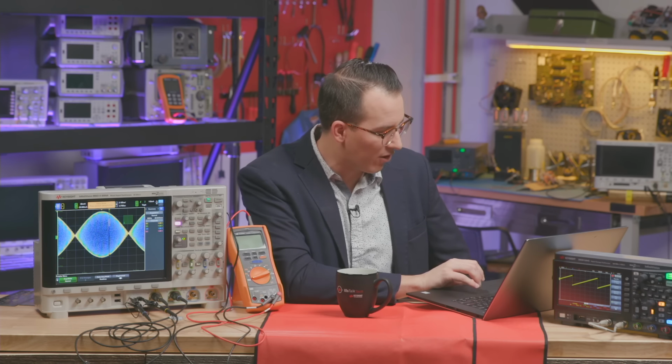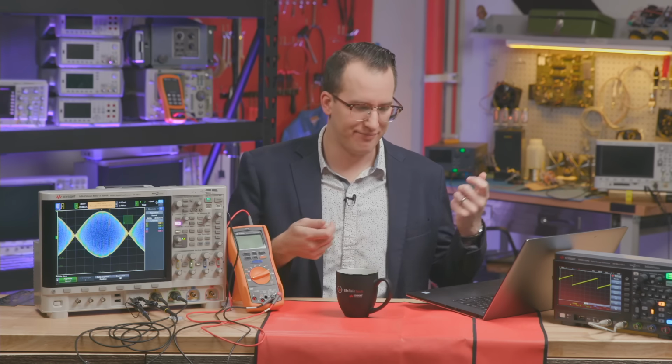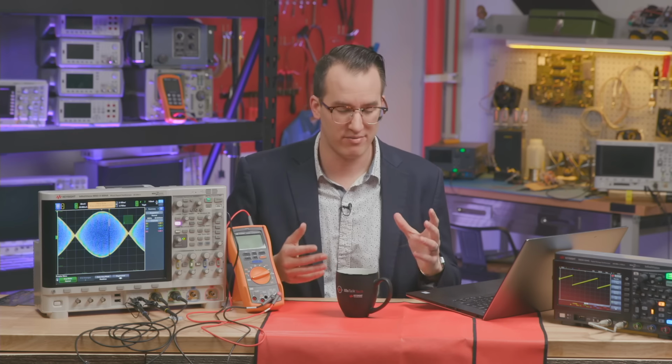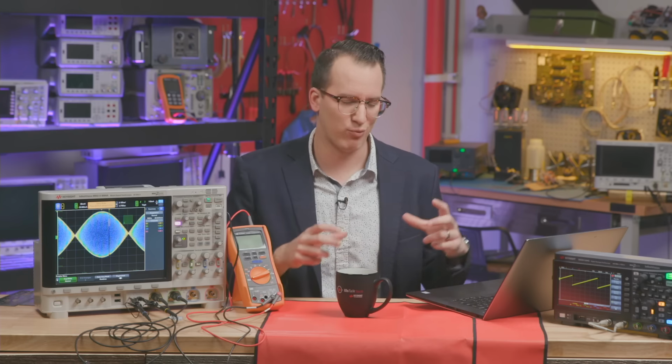How do you make sure the scope will fit the exact job required? So basically, how do you make sure you get the right scope, one that's usable for you? The most common spec is bandwidth. Look at the fastest signal you need to measure, and you want to get a couple times that bandwidth. So if you have a 100 megahertz clock, for example, you'd probably want a 200 or 300 megahertz scope to measure that. The live stream on Monday talked through how to measure bandwidth. If not, there's a video on our channel I put together a year or two back about what bandwidth is and how to pick that out and make sure it's right. So if you just search our channel for bandwidth, you'll find that video.